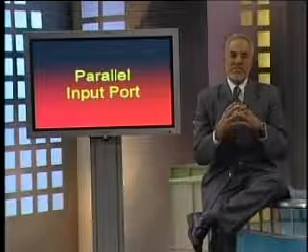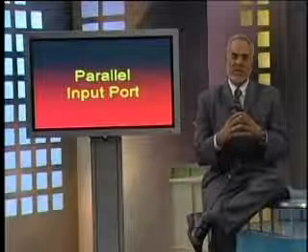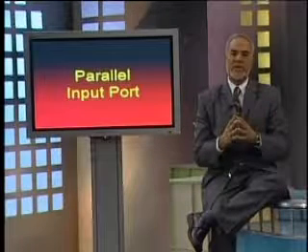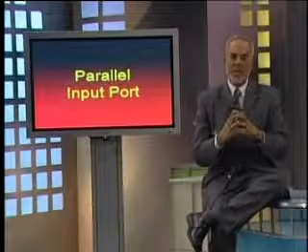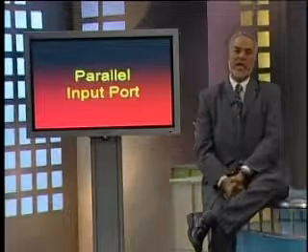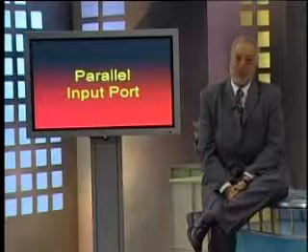In both cases, we utilize the total bus, all 16 bits together, no splitting, no independent addressing, and the addresses would be automatically aligned. That means the addresses used would all be divisible by 2.